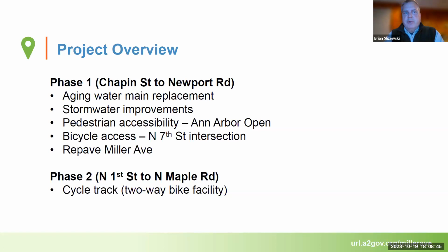That's the entire stretch from Chapin to Newport. There's also opportunities for stormwater improvements. We are in the Allen Creek drainage basin, and we do actually have a separate pool of money that looks for opportunities to provide some stormwater management, stormwater capture, before the water gets to the Allen Creek itself. So we're going to be looking at opportunities where we can to implement some improved stormwater management.